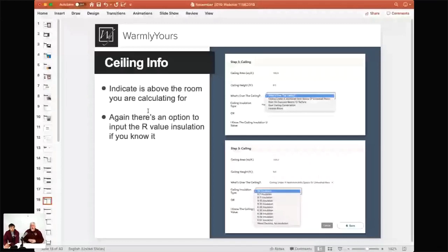That's the thing. If you're doing a first floor, you don't put the total square foot of the entire first floor. You put the square footage of the den. You do a room construction for the kitchen. You do a room construction for the den, and so on and so on. So this isn't just a mass thing for the first floor of the house. It's each individual space in that house.